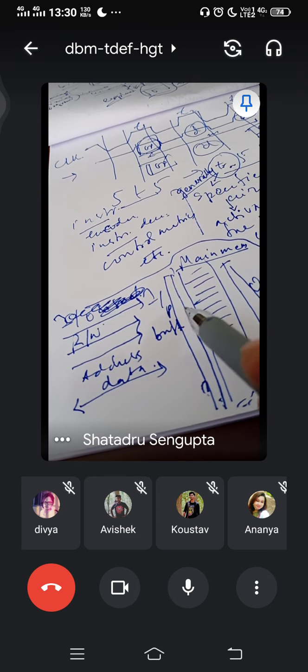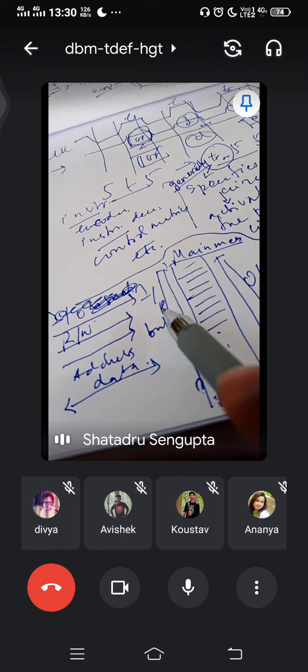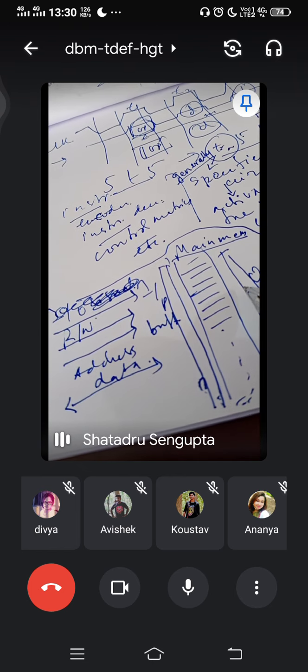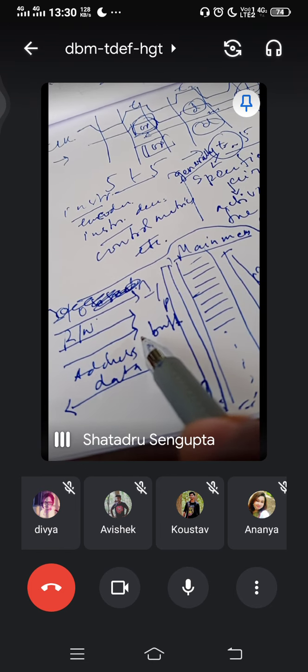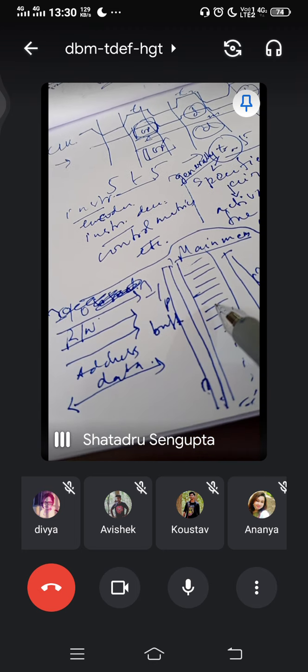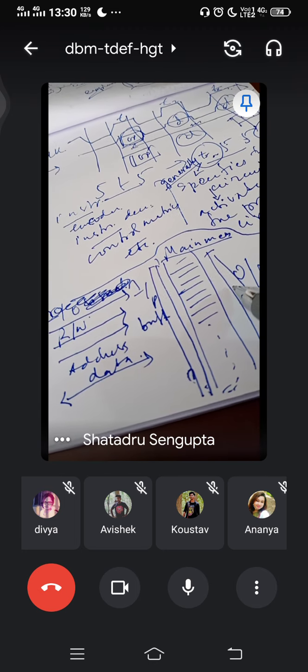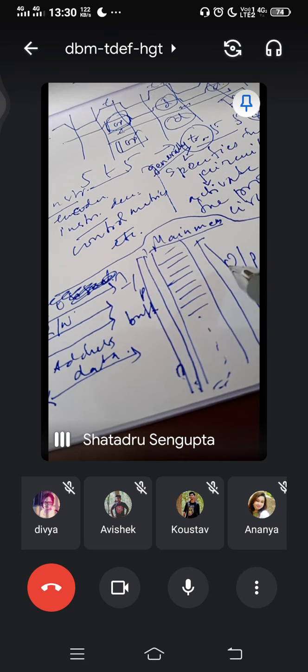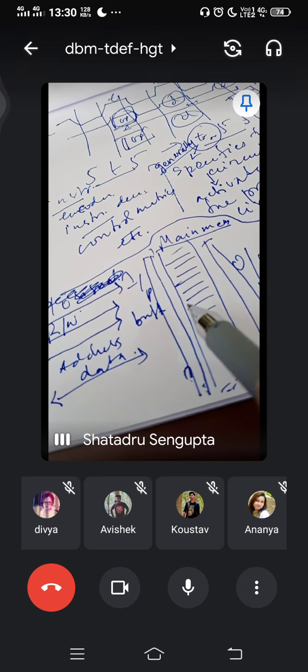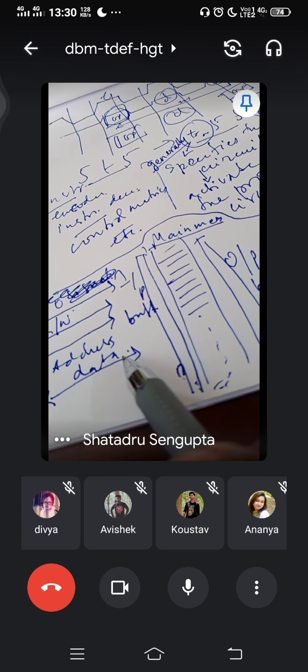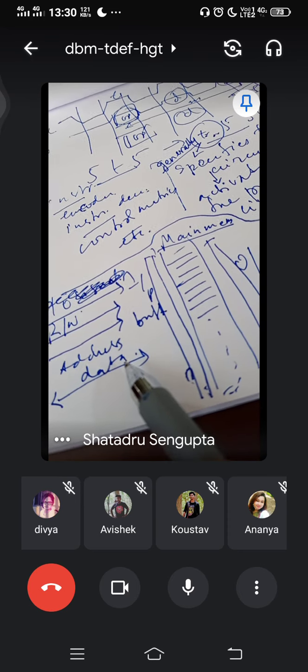And then say if you are reading it, input buffer is off, output buffer is on, and when address is selected, that data is visible through the output buffer so that the signal is copied in the data bus.